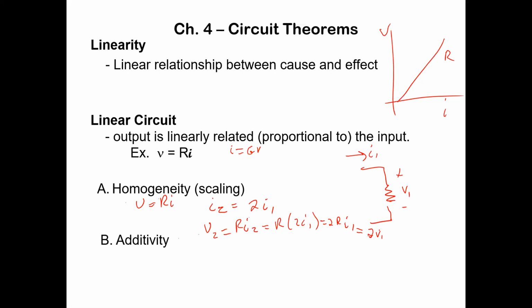And yet this is actually useful. In statics, we were solving problems like, what's the highest load this system of cables can support. This is a linear system, right? You can put a load of 50 pounds on the system and figure out what the forces are in the cables. And if you still have a lot of extra room, say the load in your cable is 100 and the cable goes up to 200, you can double the load, because everything's going to scale proportionally.